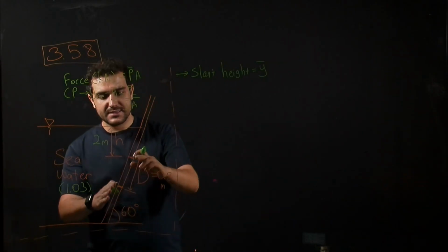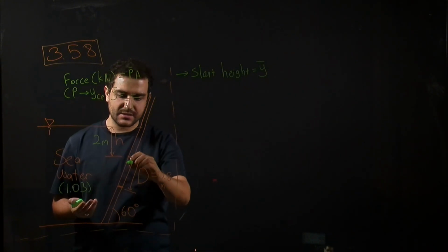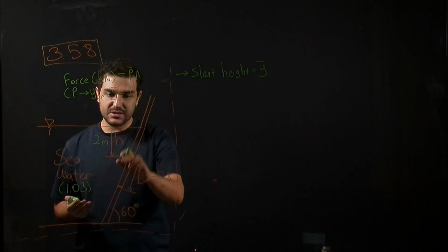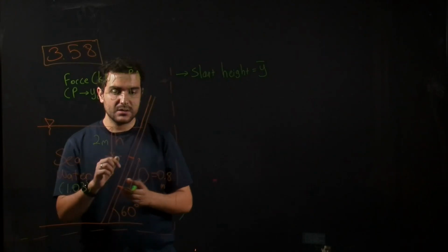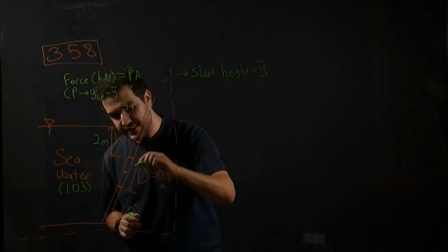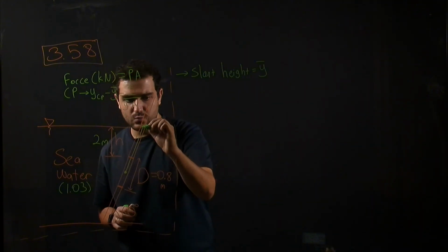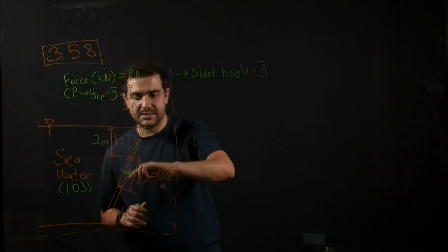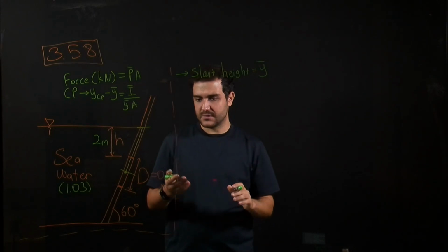So here, since we have a slant, we cannot directly find this height as depth of the centroid, but later we are going to calculate depth of centroid as well. So for this one, we need to find the height from the centroid to the water surface. So we need that slant height. So it will be the centroid of window.